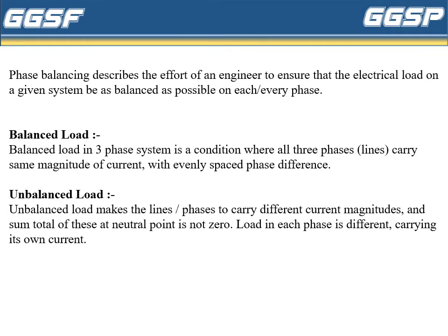Phase balancing describes the effort of an engineer to ensure that the electrical load on the given system is as balanced as possible on each and every phase. First, what is the balanced load? Balanced load in a three-phase system is a condition where all the three phases, or we can say lines, carry the same magnitude of current with evenly spaced phase differences.